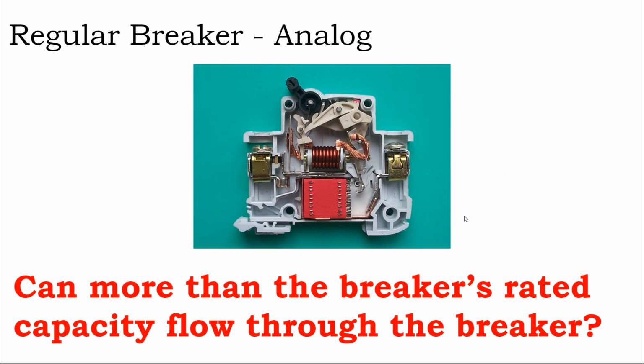So how does a breaker work? When there is a ground fault, how does a breaker know that and interrupt it? Well, not all breakers have ground fault detection built into them. That GFCI breaker is the one with the little push button on it. Not all the breakers on your service panel have that. So what do regular breakers protect? Regular breakers are your overcurrent protection. If this is a 40 amp breaker and you've got 40 amps going in and 40 amps coming out, once it goes up to 41 amps,